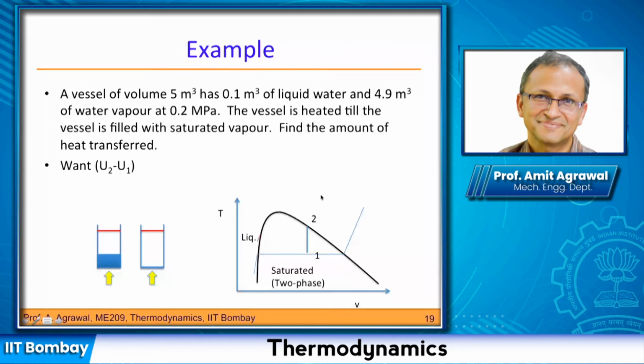After that, it will become superheated vapor. And it's not somewhere in between either, because in between you have both liquid and vapor, so it is not just saturated vapor. So it is not before and it is not after. It is at this point here at x equal to 1. So essentially, looking at the intersection of these two, keeping constant V, drawing a vertical line, your point of interest is where it intersects this black curve here. Does that answer your question?